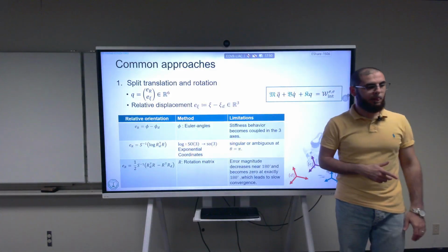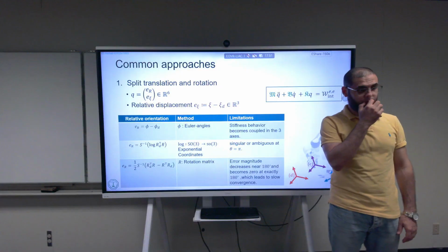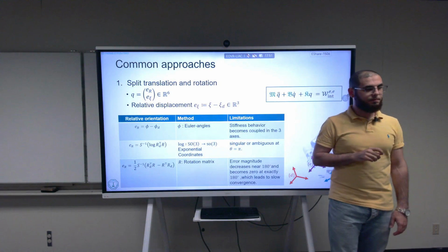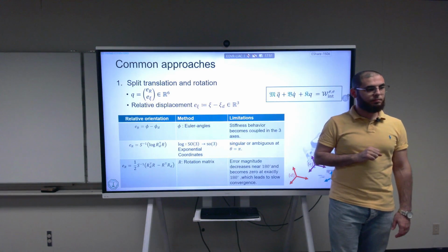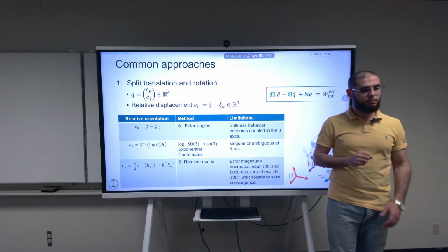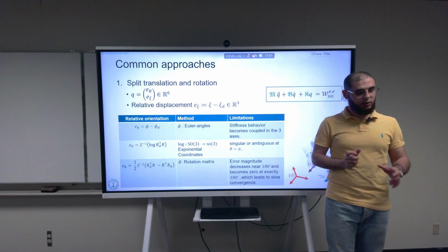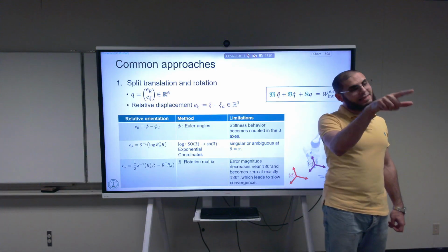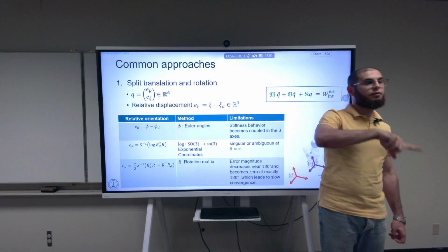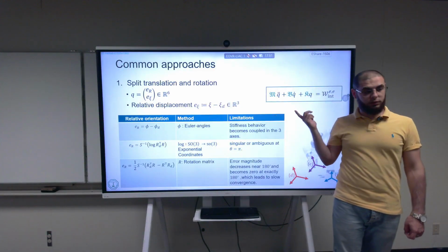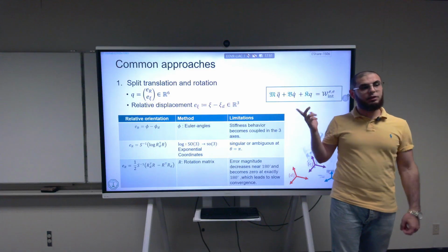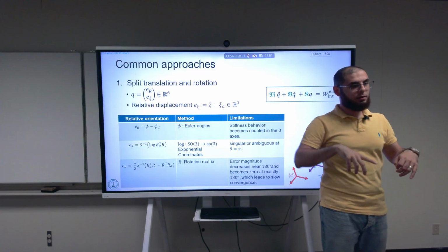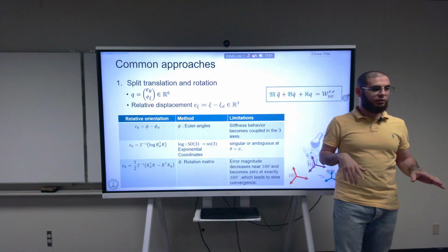Yes. For the inner angles, I still don't get why there is cross coupling between the angles when you subtract them, because for each one of them you're just taking the difference, and this difference will create some torque from the actuator in this direction. That's right. Why is there a cross coupling? When that same torque gets applied on the robot, does it make the robot end effector move in a Euclidean space? No, of course. So that's the whole idea.